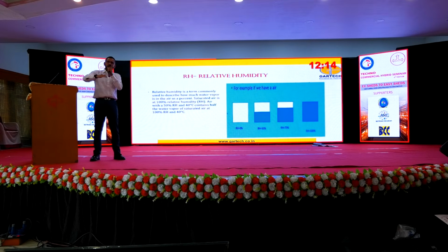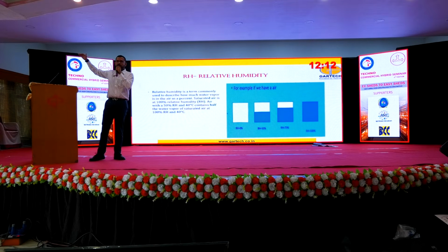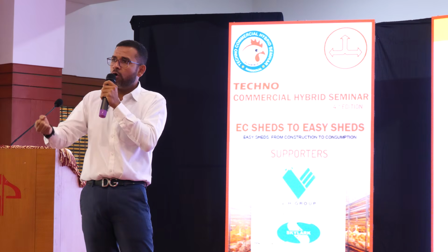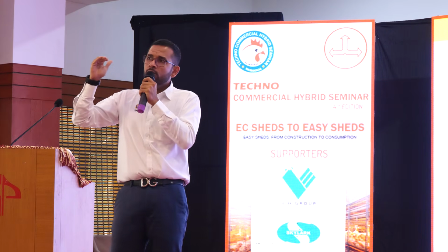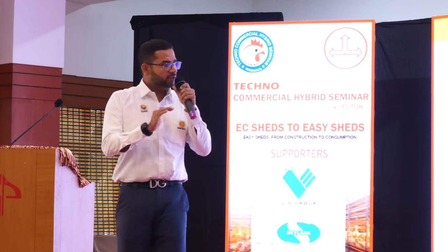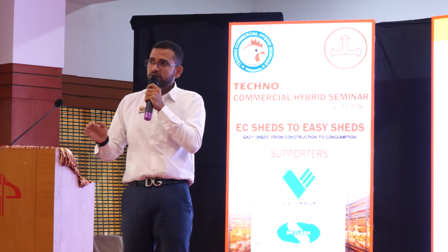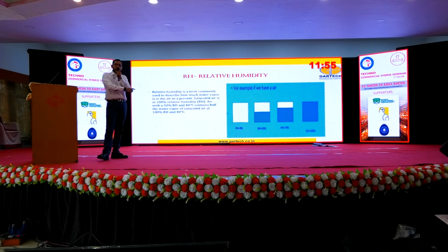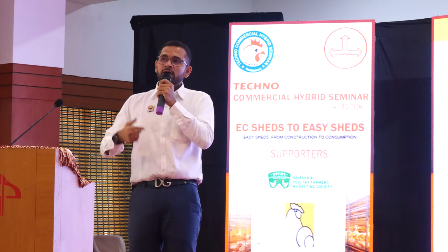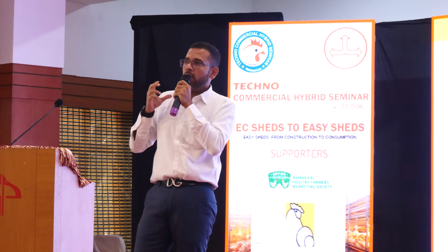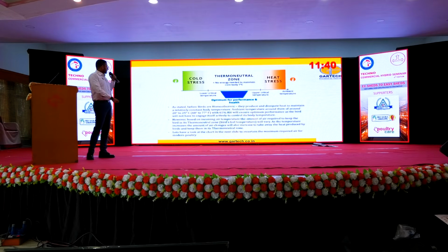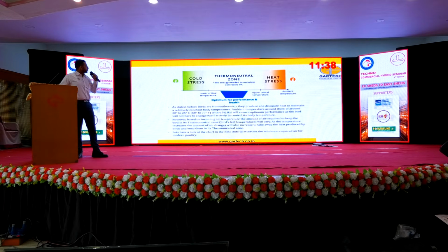And as your relative humidity starts going up and up and up, the capacity of this air to absorb excess heat is going to drop significantly. So this is a very, very big factor. In air conditioning we don't have this issue, but in an evaporative cooling system, this becomes a major issue. And if we don't consider that, then your EC houses are not going to function the way they are supposed to function.